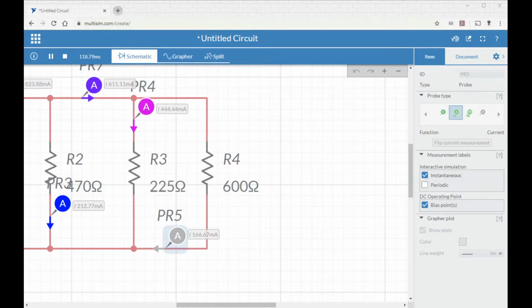Okay, so Nick, if you were measuring the voltage on each side of that resistor, that's a different story. You have a different voltage potential before the resistor and after the resistor, but the current through that branch before and after the resistor remains the same. Just think about a series circuit. What happens in between resistors in a series circuit? It's not like the current drops after it hits the first resistor and then drops after the second resistor. That is the staircase of voltage, right? The voltage rises and then the voltage falls. But with these parallel circuits, each branch is consistent.